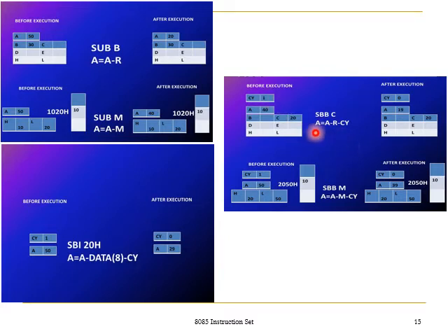After execution, 40 minus 20 gives 20. 20 minus the carry bit 1 is 19. So 19 is stored in the accumulator, and while performing this SBB operation no carry is generated, so the carry is cleared.